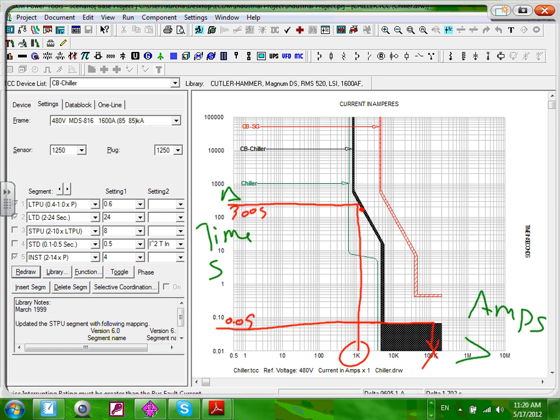Divided by 60. Yep. You're allowing, but remember, the sensor is sitting at 1,000 amp. So 1,000 amp, guys, in a 1,200 amp circuit breaker is a load, not a short circuit. Anyway, so that's what these curves give you.